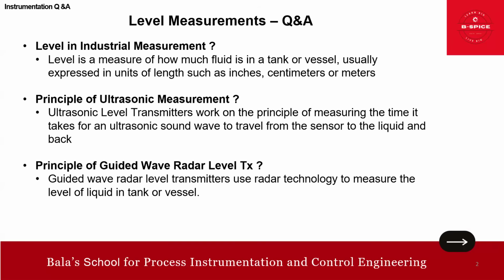When radar pulses reach a media with a different dielectric constant, part of the energy is reflected to the transmitter, and the remaining passes down. The time difference between the transmitted and the reflected pulse is converted into a distance from which the total level or interface level can be calculated. So this is the simple principle of guided wave.